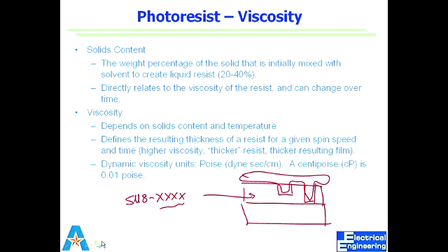So we make features, and instead of making features in the underlying wafer, we make features in the SU8 itself, and use those features to translate into microfluidics. It is a resist. It's a photoresist. So the feature is made in the resist and then it is done. Because SU8 can give us very thick features. If you look it up, SU8, you'll see that they come in 50 micron thickness, 100 micron, just very, very thick.